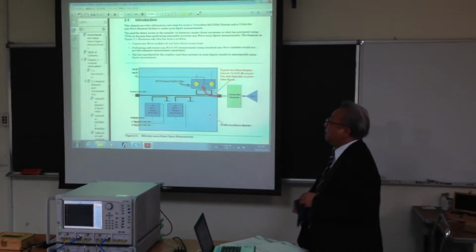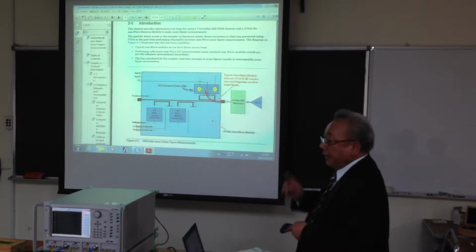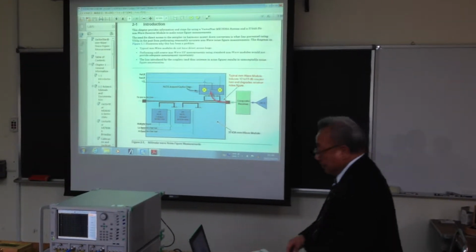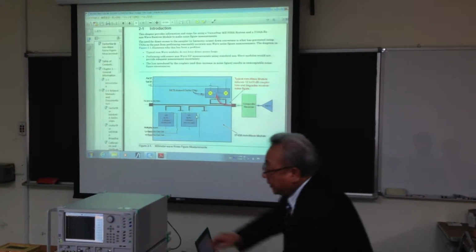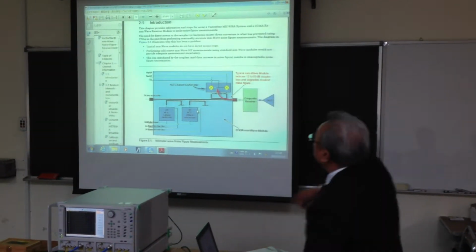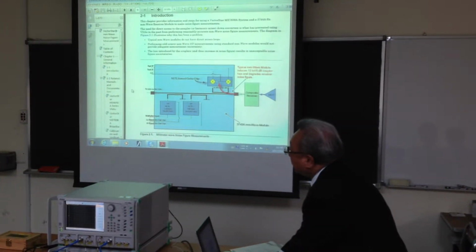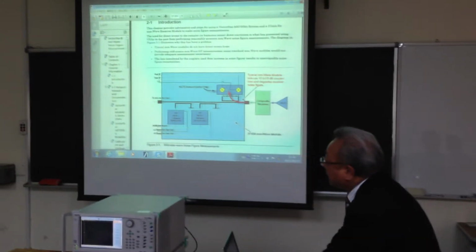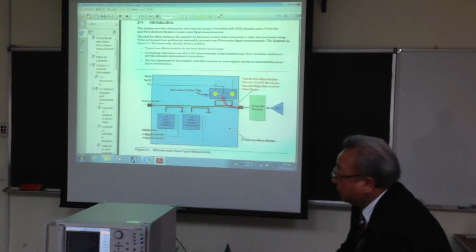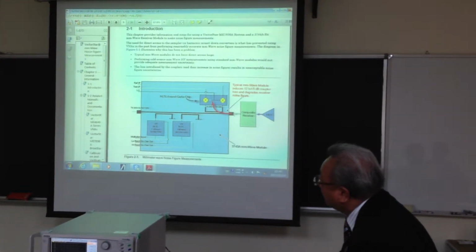The standard is the transmission and reflection module, and there is the receiver only module. This is a block diagram of the standard module. This module takes the through path from the VNA up to the 54 gigahertz signal, and through to the 1 millimeter connectors.